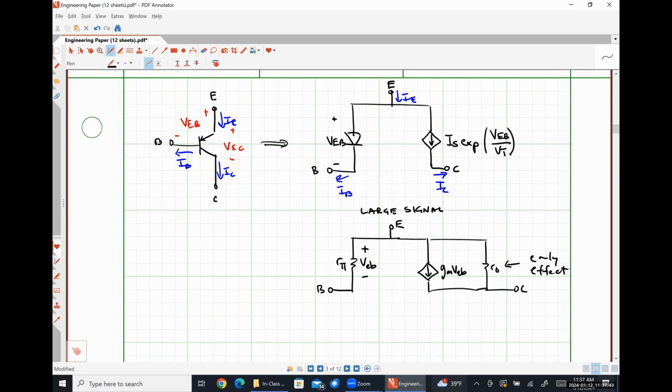Unless you guys want me to talk more about BJTs. Yes. And it is the same exact equations that we used for NPN BJTs. So it'll be VA over IC, if my memory serves me correctly. I guess I could probably look. No, I didn't bring those notes with me, but anyway, the exact same equations as before for calculating our transconductance and calculating R pi and calculating R naught. Literally the same relationships.